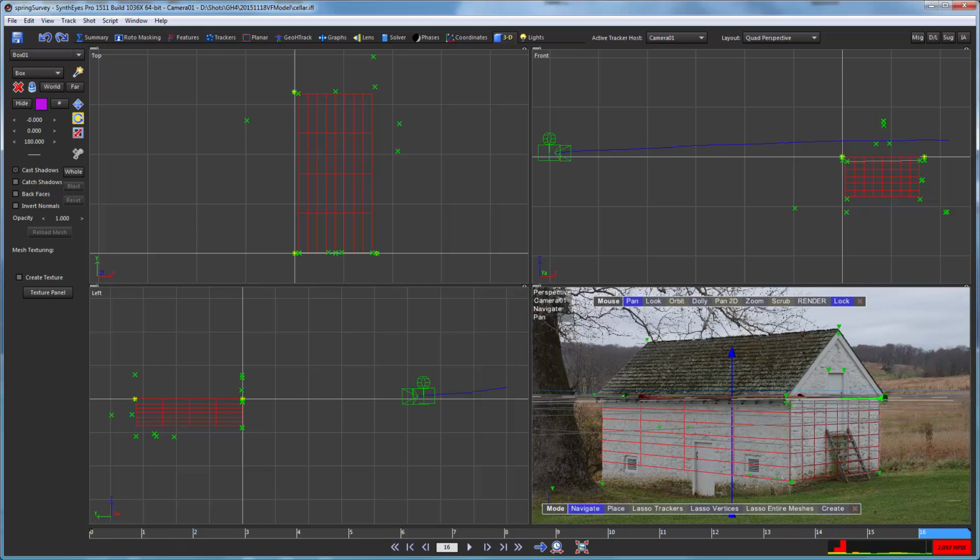And let's go to the end of the shot. And now you see from the side view some more of the details of what we want to do. First, we're going to go and select the numbers tool there that allows us to adjust the degree of subdividing, if you like, of the box. So let's just jack that up a bit, so maybe around 15, 16, something like that. We get a nicely decimated side there that kind of matches the other one. So that seems more tractable.